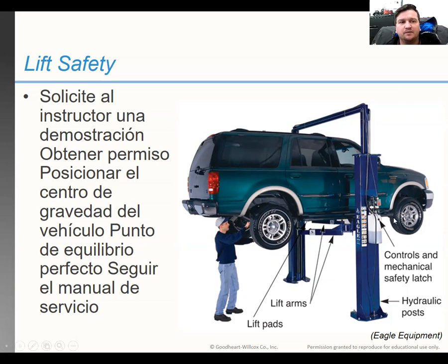You can look on the side of the lift here. These are the controls you're going to use. These are the lift arms, and the lift pads are what's going to actually contact the frame and lift the vehicle up.